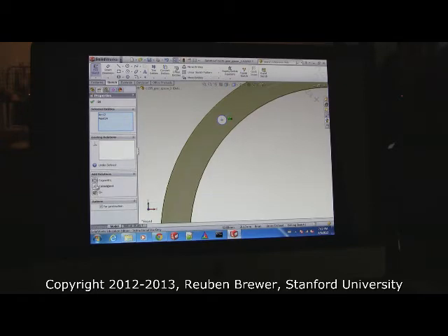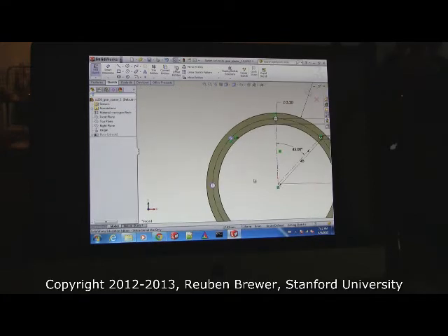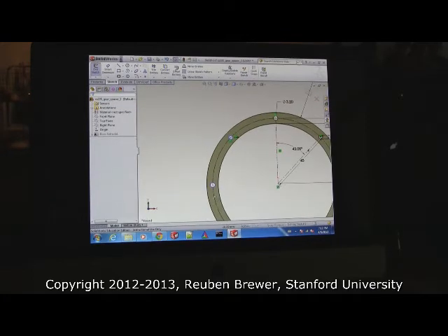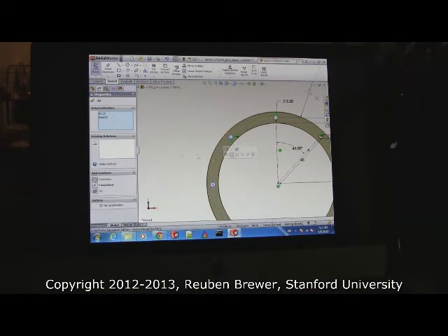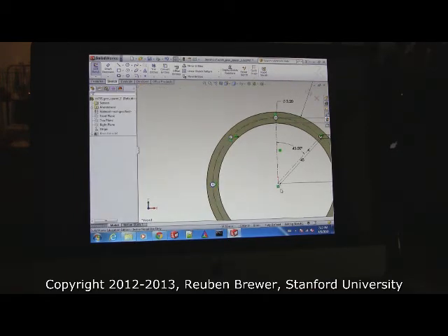So now the other two options are either coincident or concentric. Concentric means it's going to take that circle and place it at the middle. We don't want that. We just want coincident. That means that point that we clicked will be on that circle. We're good. Now hit the check mark OK. We're still blue. It actually takes 2 of these, I think. So now do another blue circle. Click the center, click the diameter, hit coincident. Boom! We're black.